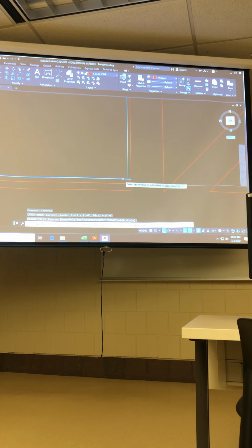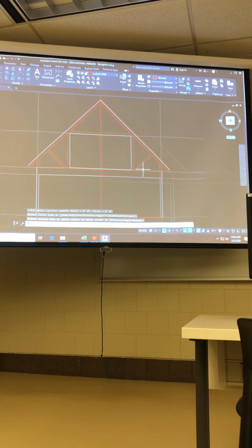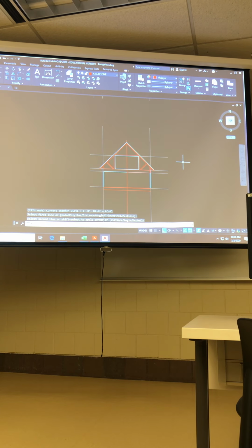How thick did you make the dimensions there? 3/4 of an inch. Yeah. And that's kind of a standard dimension. There's no real precise thickness because those floor finishes can vary. It could be wood, it could be carpet, it could be tile floor finish. I'm just kind of assuming and giving that a 3/4 inch thickness regardless of what it is. Okay, nothing magic about that one.